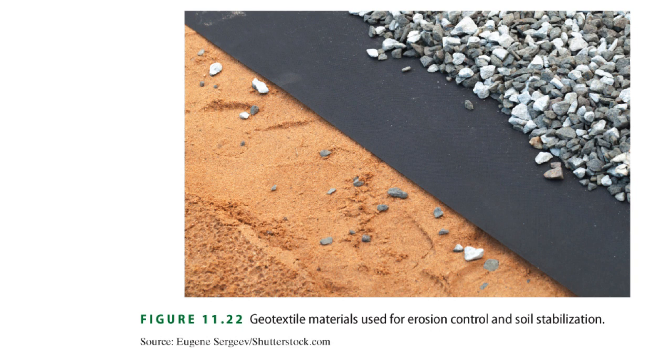Steeper slopes may require synthetic geotextiles and turf reinforcement materials, which will lock the soil in place but allow the water to permeate the soils. Geotextiles are synthetic materials purposely designed to protect soil and manage water flow in a variety of ways. They're easy to install, but can be unsightly and expensive to implement and repair.